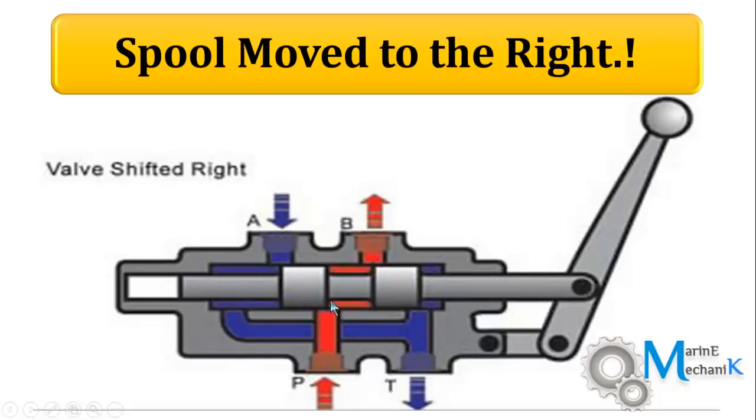So the high pressure oil from P passes through B and then it works on the hydraulic motor or the piston, and then the exhaust, the low pressure drain oil, comes through A and drains back to the tank through T. So it takes a cross path, P to B and A to T. This is how it works when I move the lever to the right.